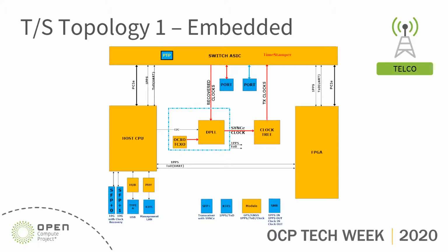One is some source of frequency or clocks for the node, and then a way to run the PTP algorithms. And so typically the frequency is done off a Sync-E, which is done off recovered clocks from in-band Ethernet traffic on a particular port on a node.